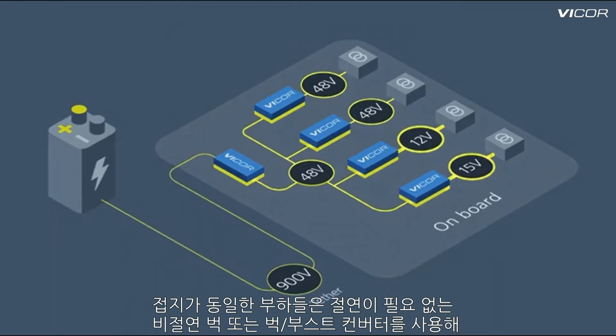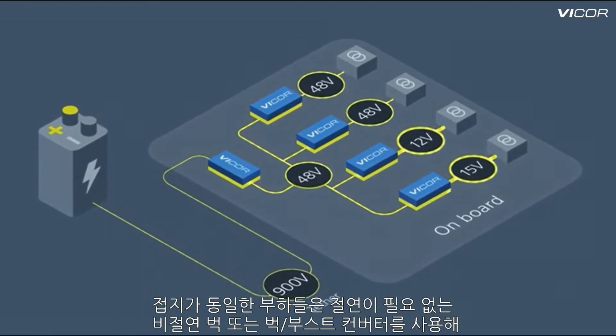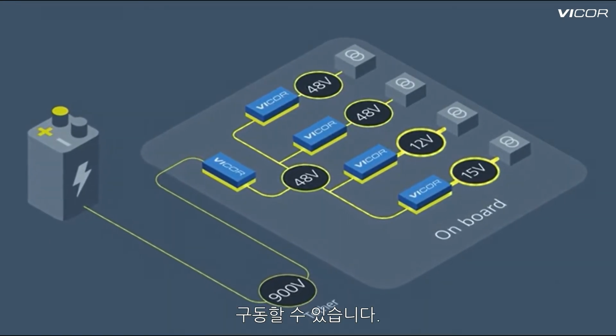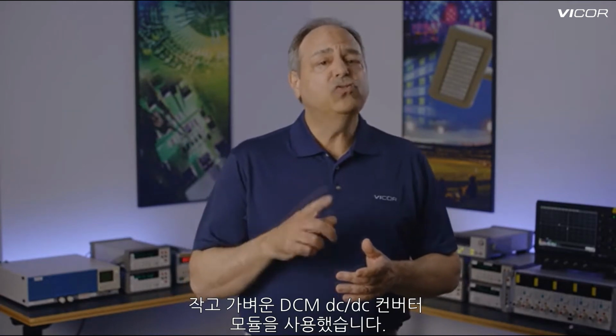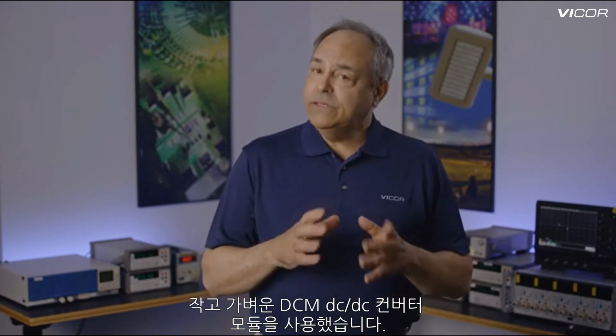So the first key component is the high-voltage fixed ratio converter, boasting greater than 97% efficiency, utilizing a transformer-based series resonant topology without regulation, making for a clean, low EMI, and highly efficient conversion. Loads with the same ground can be powered by a non-isolated buck or buck-boost converter without the need for isolation. The camera and sensors need a separate return, isolated from others, so using a small, lightweight DCM, DC-to-DC converter module was acceptable. A thin bus wire was run across the vehicle to the loads, and each has its own converter.